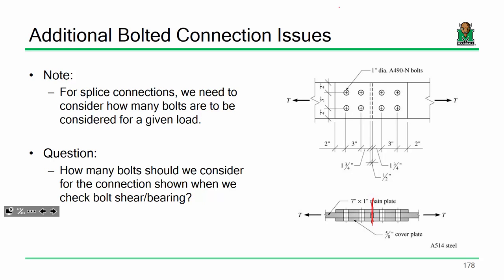Yes, sir? So do the cover plates see 2T? No, they see half a T. Yeah, because that's just basic statics. If I cut a section, I've got T going this way, so each one carries half of that. Does that make sense?